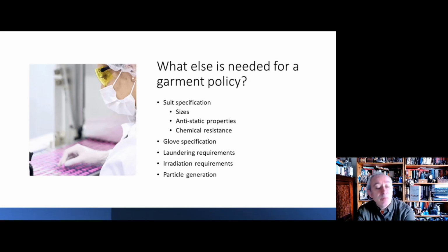Another thing with all this kind of clothing aspect is that it's also very important to wear clean room suits, gloves, masks of the correct size, which is why there are different sizes available. If you wear a clean room suit that is too big, then it will create air pockets and there is a risk of pushing particles out. If you wear a clean room suit that's too tight, you can't really move and it's incredibly uncomfortable.